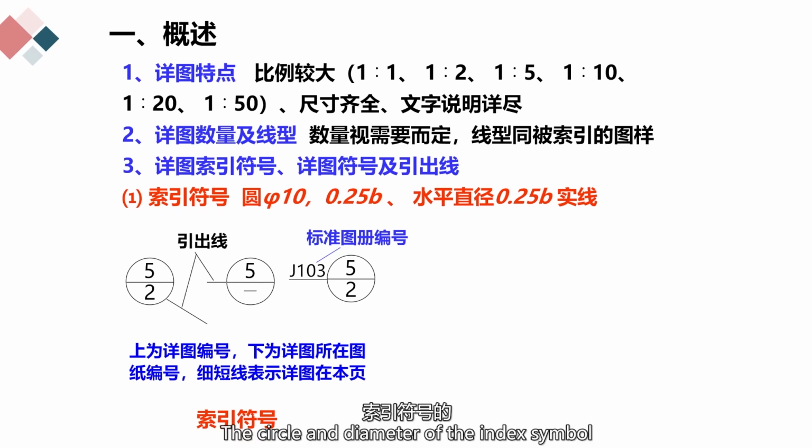The circle and diameter of the index symbol should all be drawn with thin solid lines, and the diameter of the circle is 10 mm.